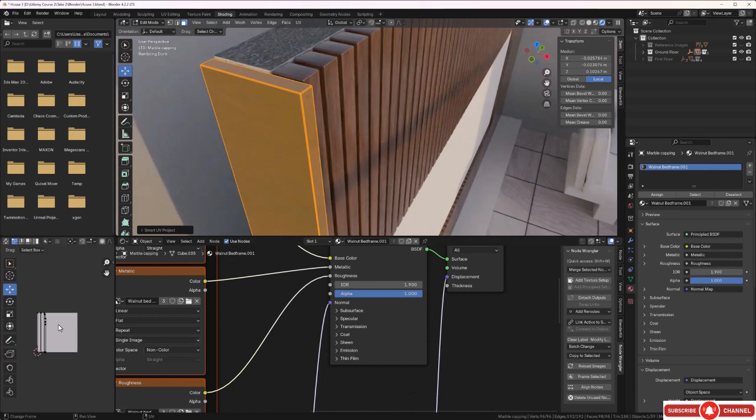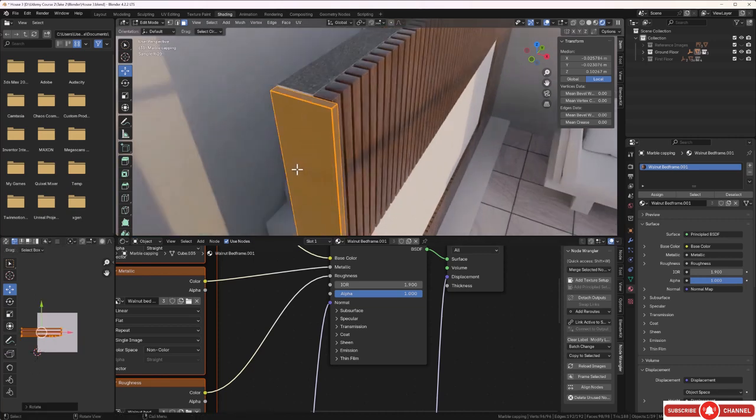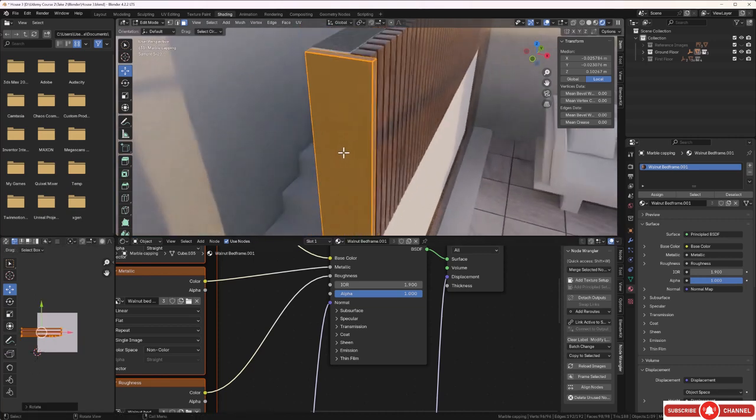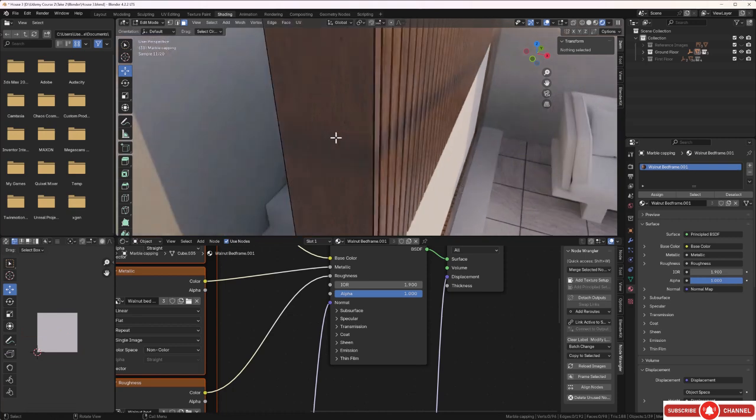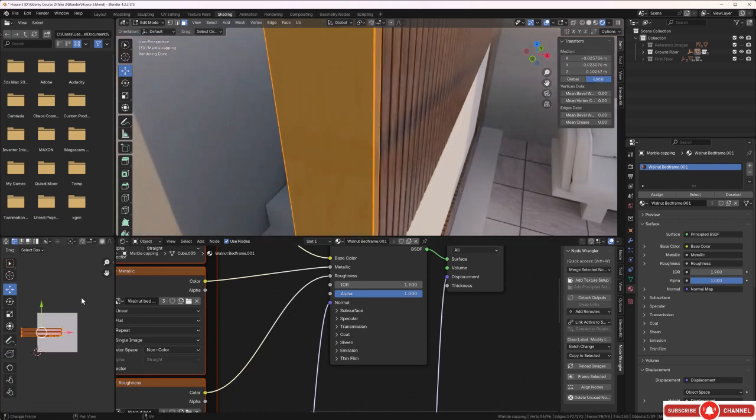So I think then let's go ahead and grab everything and rotate it. So we'll press R, 90, enter. And let's have a look at the scale on that. And yeah, it's repeating. I don't like that. So I'll press A for all again. And I'll hit the S key and bring this down in size.